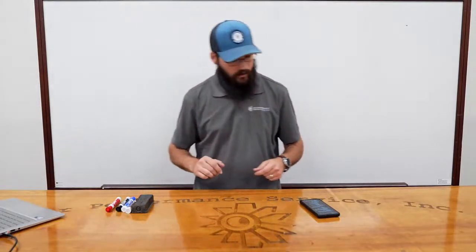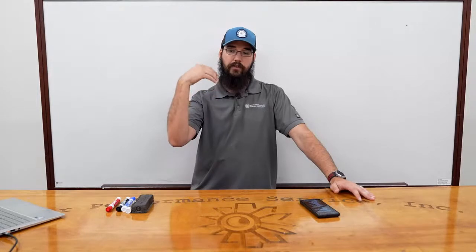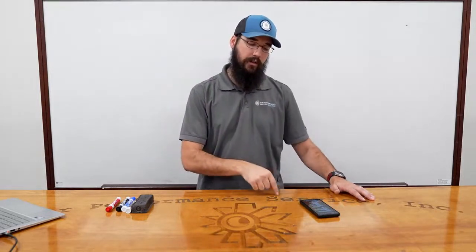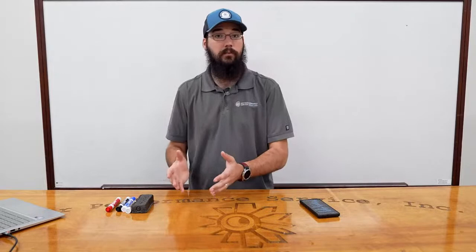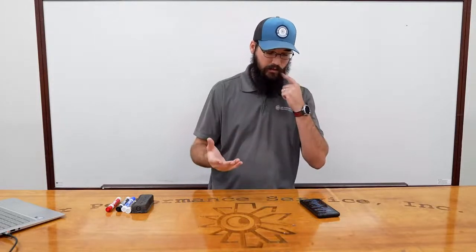Let me silence that. So how do we measure the air? There's a handful of ways. So CFM is one. CFM, as I've already explained, is a way to measure the physical volume. We can use static to also measure air, but it's a different type of measurement. It's about how the fan is responding to the design or the duct system itself, and what's happening with the way the system is functioning. So that is where static plays a big role.